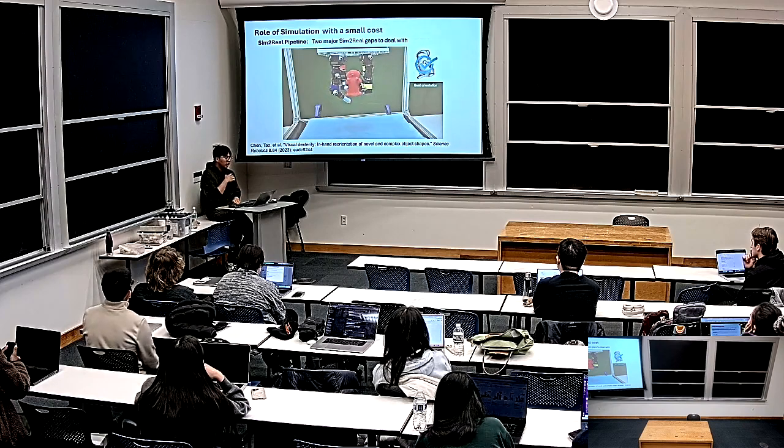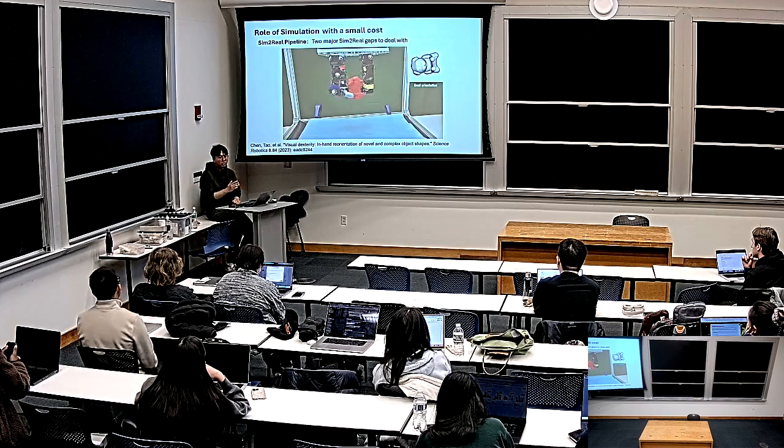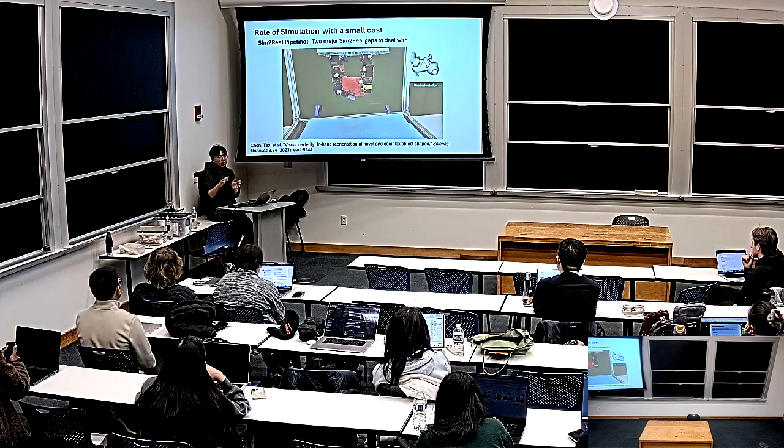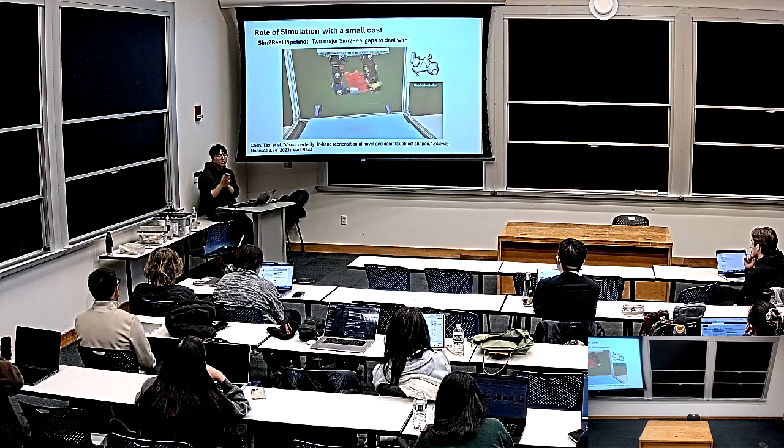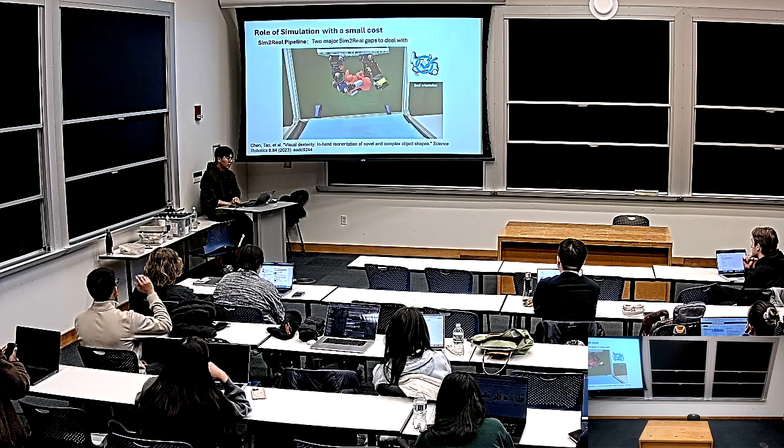The technique that Tao used to transfer this simulated policy to the real world is a combination of both: doing domain randomization on these parameters, but having a good guess of those ranges by doing some very basic system identification.